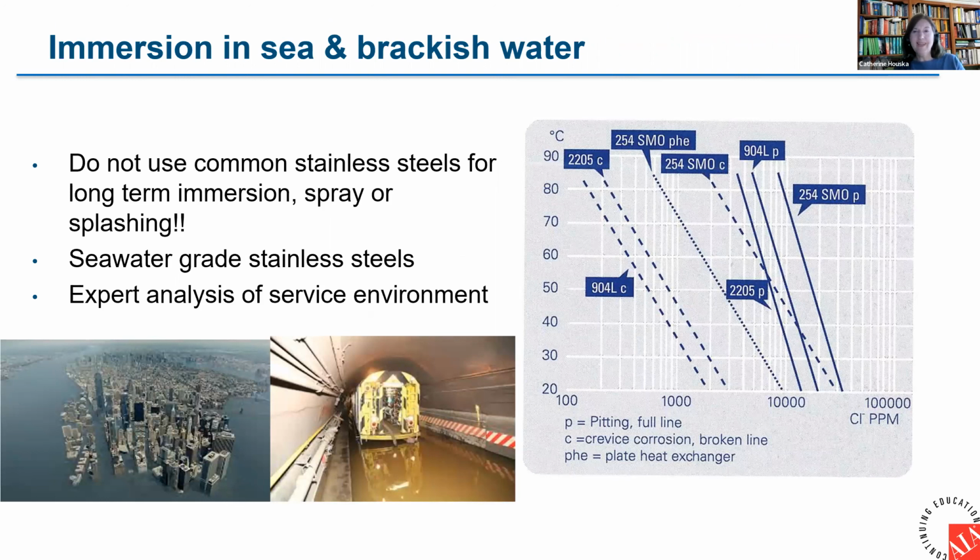If you are designing a project that's going to be one of these new developments that's going to be floating on water, well, you really should consider whether the materials can withstand salt water. 316 most definitely is not a seawater grade stainless steel. The stainless steels or any of the metals in general that are necessary to withstand salt water are far more corrosion resistant.